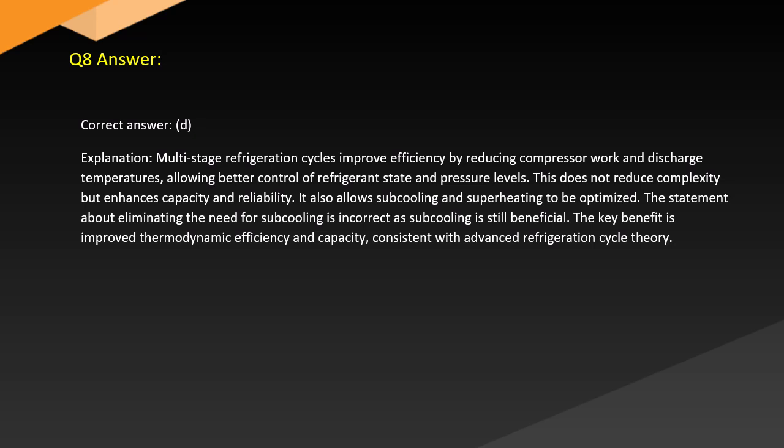It also allows subcooling and superheating to be optimized. The statement about eliminating the need for subcooling is incorrect, as subcooling is still beneficial. The key benefit: improved thermodynamic efficiency and capacity, consistent with advanced refrigeration cycle theory.